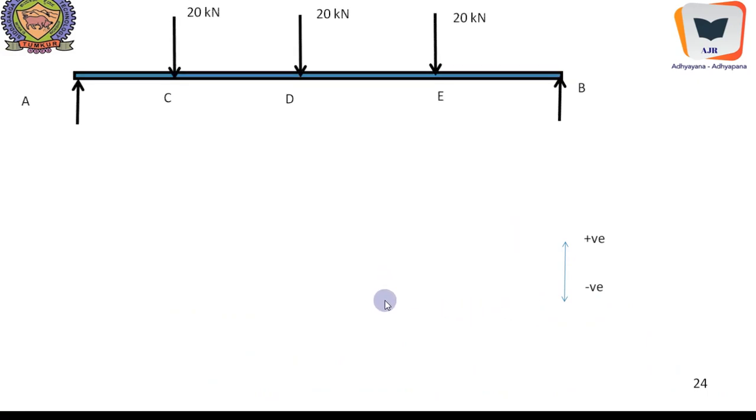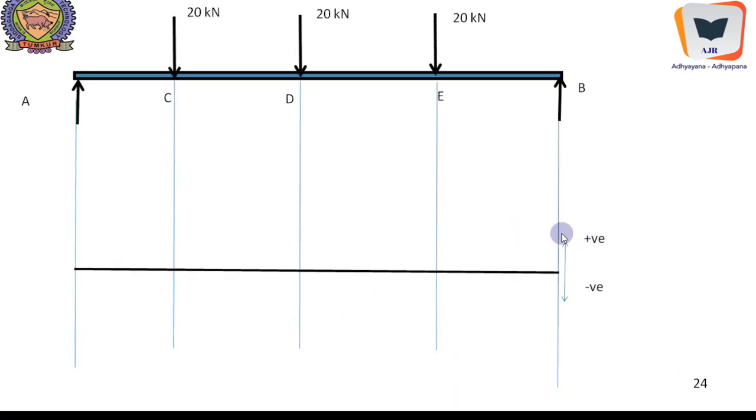Right, we will plot this. We have calculated already. This is the positive bending moment value, negative bending moment value. The beam axis is taken as a reference. This is a graphical representation. This should not be confused with the bending nature of the beam. It is not the bending of the beam which is picturized, rather it is the magnitude of the bending moments which has been graphed. So typically a bending moment diagram is a graph showing the variation of bending moment at various sections.